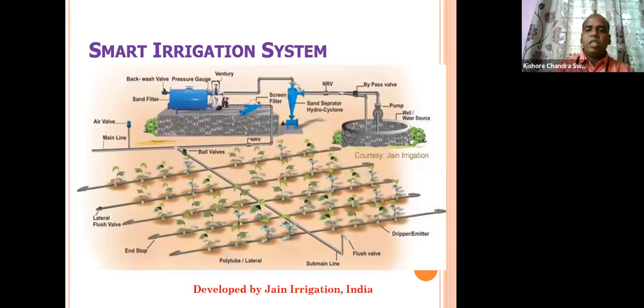And in this irrigation work, they are developing a smart irrigation system where they can measure the moisture content in the soil, and on that basis it will automatically start the irrigation system, particularly a drip irrigation system, where the plant will be irrigated based on its requirement, not the flooding system. We go for irrigating the water, and sometimes you don't know how much water is required.